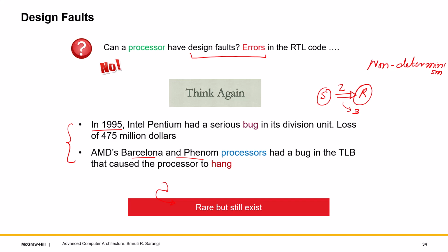And many modern approaches are also taking the patch direction seriously. If, let's say, the implementation of some instruction is wrong, we can replace it with a sequence of microcode which has the correct implementation. It will be much slower, but the point is that the microcode stored in firmware will at least give you a correct output. So such hardware patching is also happening. But the most important point is that we do so much testing in hardware because we can't afford a bug. In the case of software, it's not that much because a patch can quickly be downloaded and installed.